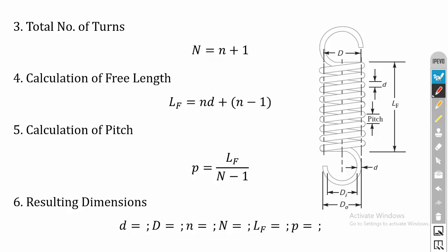Fine. So this is the drawing for helical tension spring. So this is the coil diameter and small d is the wire diameter, di is inner diameter and do is outer diameter. The distance between adjacent coils is called as pitch, and the length of the spring at the elongated state is called as free length.